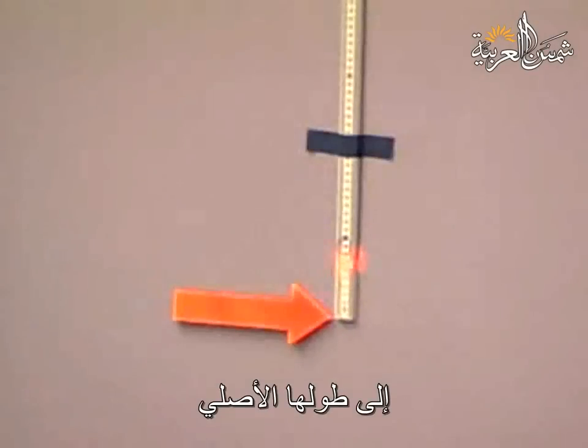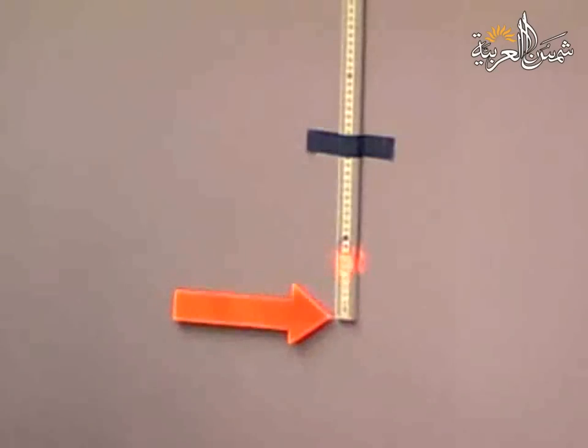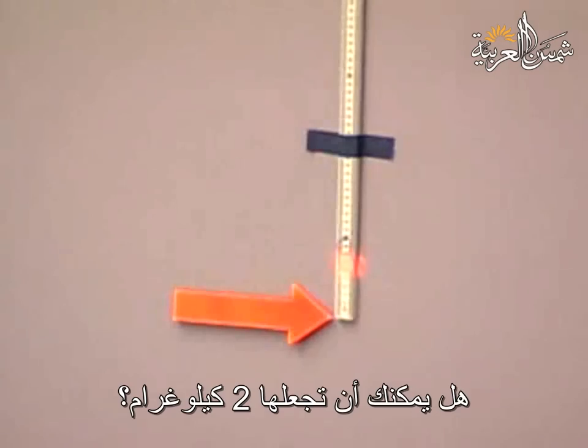Oh, but you see, it no longer wants to return to its original length. It's clearly longer now. Permanent deformation has already occurred. And so we're now something like 6 centimeters. Can you make it 2 kilograms?